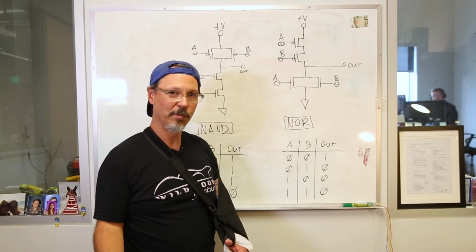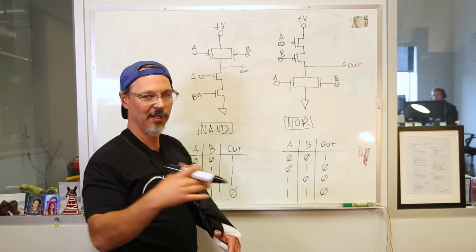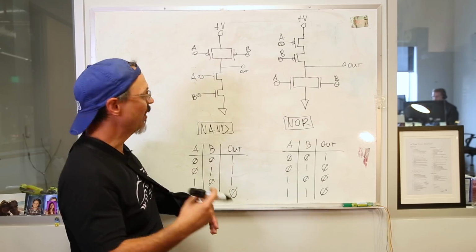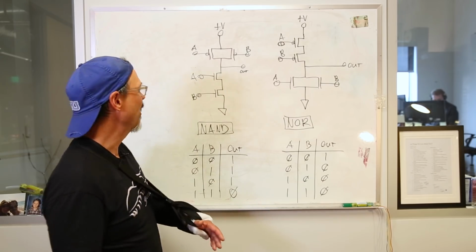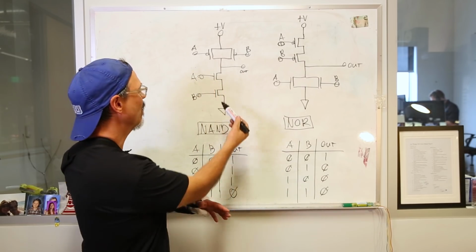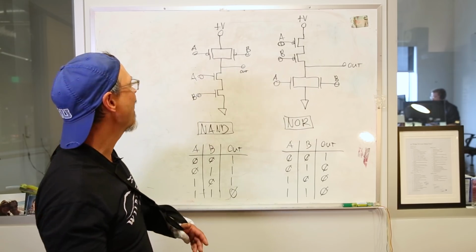Now the improvements from the previous circuit are, number one, we're using MOSFETs. So like I said, the switching time is much better. Your input impedance is also much better because there's no steering current. These are just voltages, so very little charge in the junctions. They switch on and off really fast.